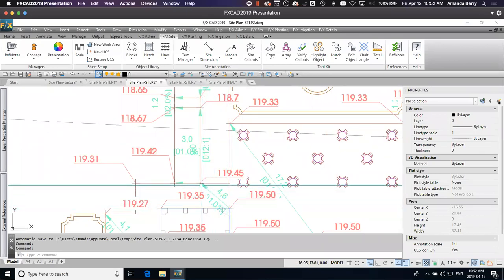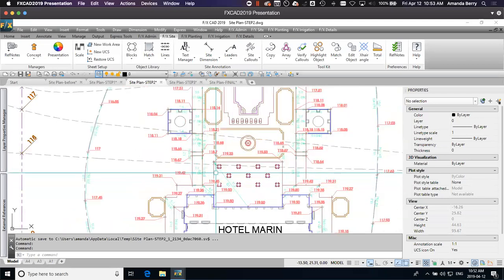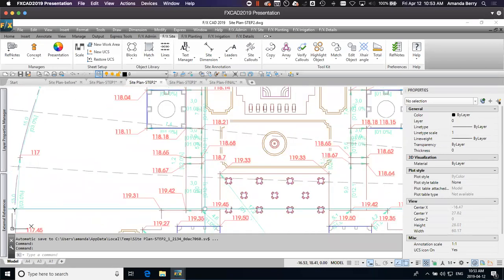I went 1% to determine that. And then I followed this along and knew that I needed a 12:1 ratio. And like you saw before, you can do grade down by percent or grade down by ratio. But what I also know is that I can only go for 9 meters, which is about 27 feet, maybe 30 feet, before I needed a ramp of about 1.2 meters or 4 feet at a certain percentage. So I went for 9 meters and then did 1.2 feet at 2% down, and then 12:1.